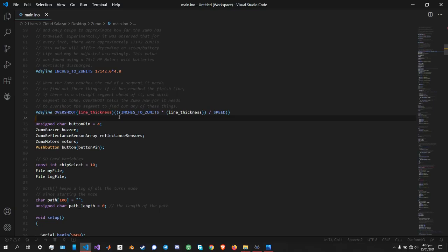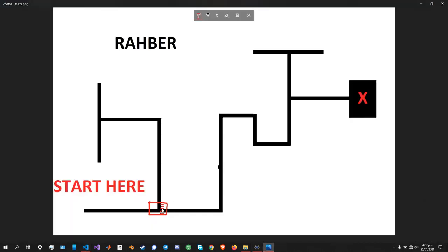So it goes above, and let's say our sensors misbehaved, or we encountered an error, and the sensor has started malfunctioning. It starts giving false signals, and it starts telling the robot that there is a line ahead, while there is no line ahead. So what we can do is wait a little.